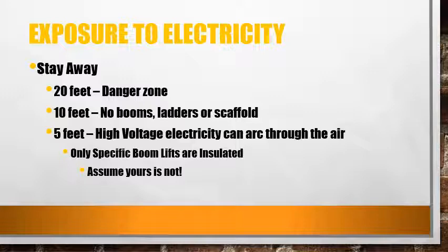If you're ever within 20 feet of a high voltage power line, you have entered the danger zone, where you must take precautions to prevent yourself from being electrocuted. Never enter a 10-feet area between yourself and power lines with any tool, boom, ladder, or scaffold. If you are within 5 feet of high voltage power lines, the electricity can actually arc through the air without